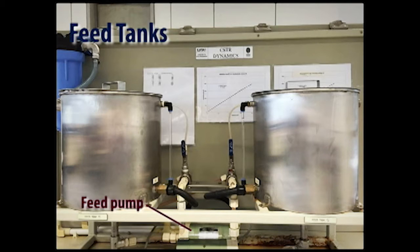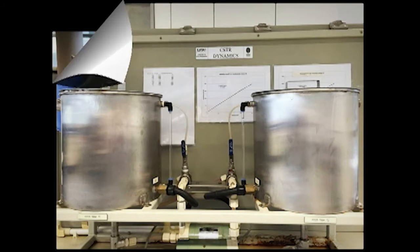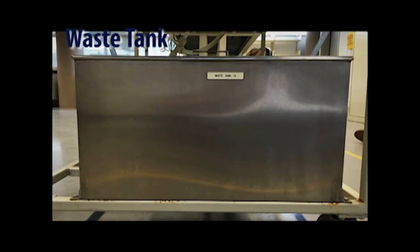Each tank has a feed pump to transfer the liquid from the feed tank to the reactor. Also, there is a level switch fitted in each tank to protect the pumps from dry run. The waste tank is a rectangular tank with 50 liters of capacity made of stainless steel. It is placed at the bottom of the equipment.